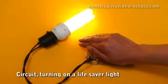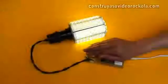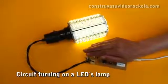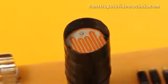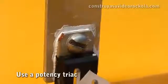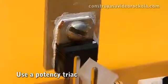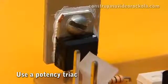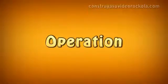This circuit operates with voltage from 115 to 220 volts, no need to make any changes. You can light a bulb up to 100 watts. If you want to power more powerful lighting devices, you should only change the BT136 triac for one that supports more amps, such as the BTA08-600, which supports up to 8 amps. Operation.